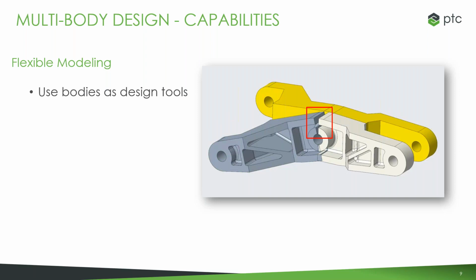And once you have different bodies, you can translate them, move them, rotate them. So like we said, you can split things into two separate bodies. So let's say you design this part, and you decide, actually, the second part that sits with it needs to be on an angle. So you could just create that as a solid, and then straight across, split the bodies and rotate half of the body. So this makes it very easy.